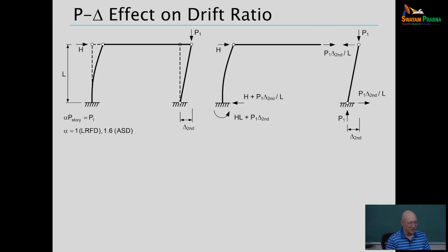I'm designing some rigging for something. I want to be able to do dead plus live. All right, so we have dead plus live now. They've sorted out, by reliability basis, what the other ASD factors should be. Problem solved, but it's been a 2.5 year mess. And if we just had LRFD and not ASD, we wouldn't have been losing all that time.